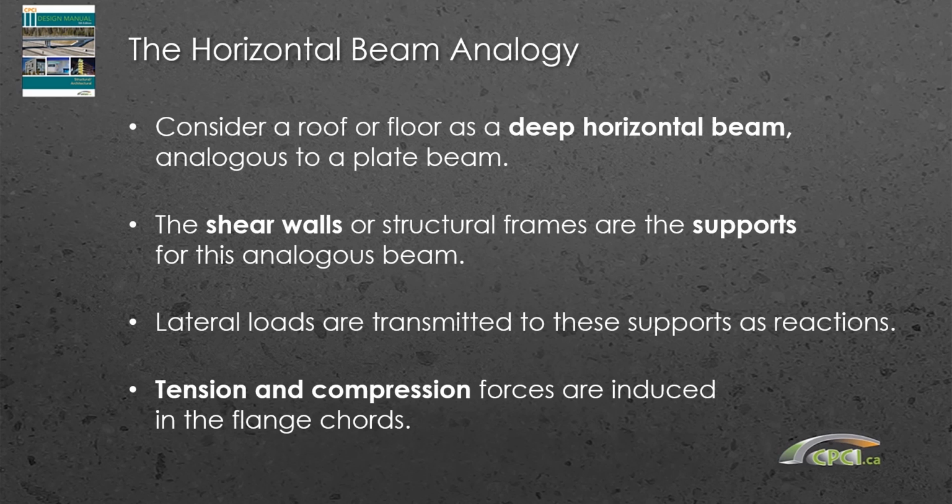So you have to look at designing the diaphragm basically for the shear and the moment coming from the structural analysis, and you will end up having tension and compression chords on the outside faces that are resisting the required loads from the analysis.